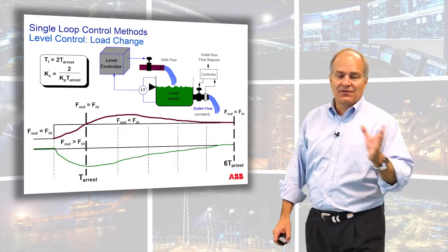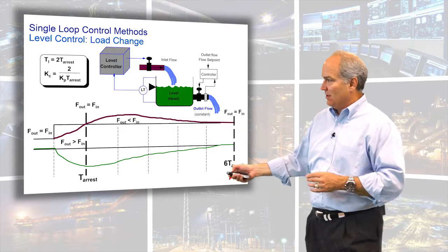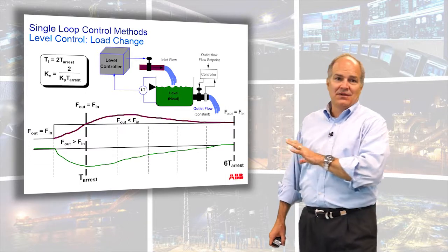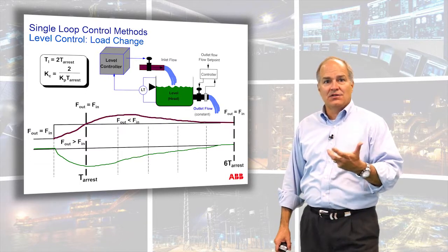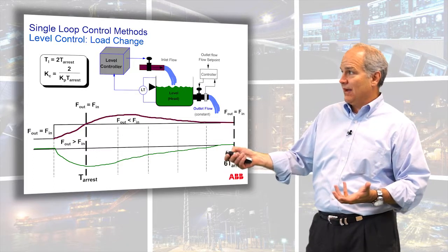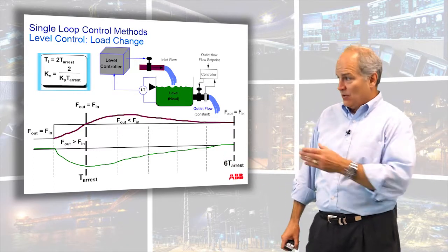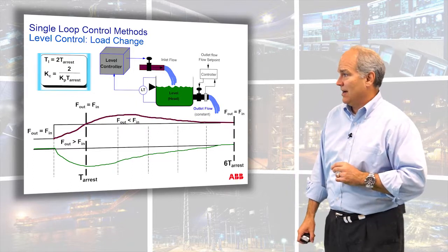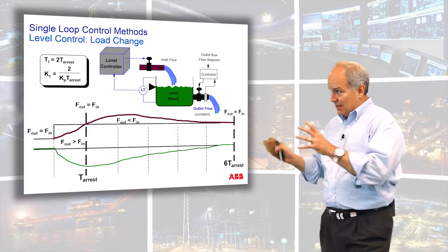And there's a lot of different tuning rules. Some people like to see this wiggle. I found this to be a very stable and secure tuning technique, and it's pretty simple. Once you calculate the fill time, you just use this equation. Then you pick the arrest rate, and I'm going to show you how to do that here in just a minute. But this is the trajectory.